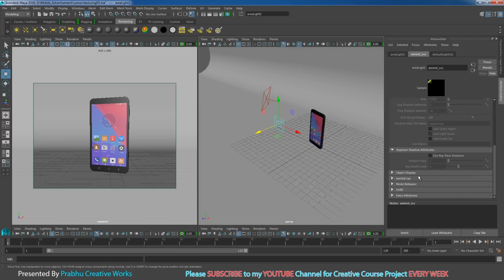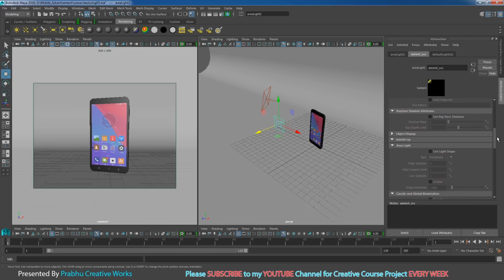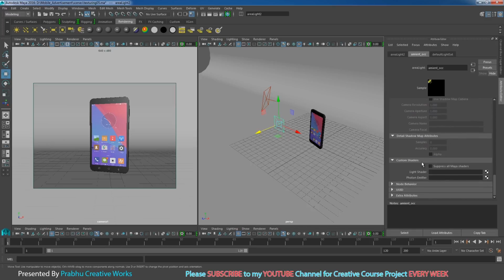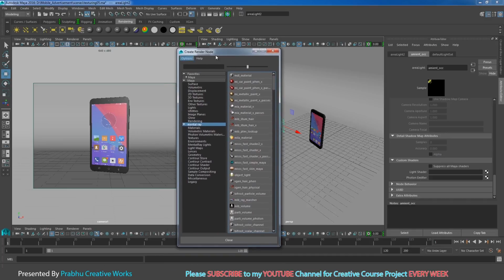So go to the mental ray option, and go down over here. Here you have the custom shader option. Click on this checker box over here. It will open your render nodes. Go to mental ray option.